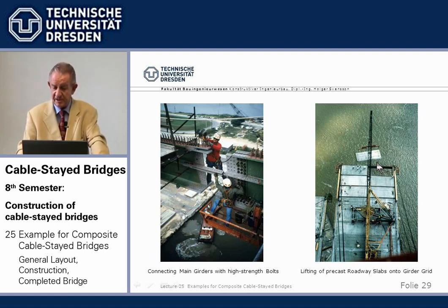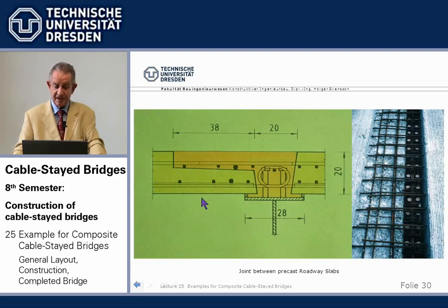We see here the precast plate piece by piece being lifted up, resting on the top flange of the cross girders, and we see here the top flange of the cross girder. We didn't need any more form. There was no additional form for the cast in place joints.